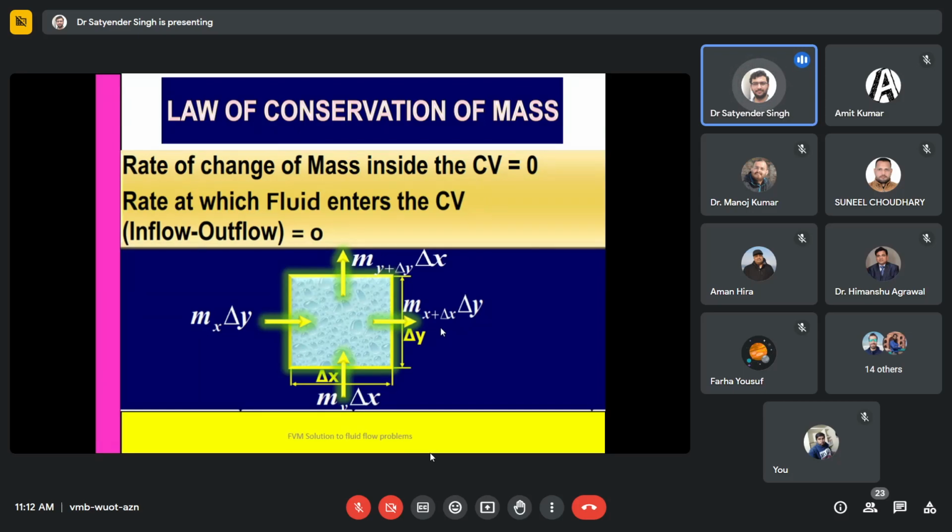The most important thing to mention is the use of this conservation of mass. Although we cannot derive any velocity from this mass balance, if you are using any CFD solver, the first thing you will see is the convergence of the continuity equation. The importance of conservation of mass in all solutions of fluid flow problems is that we check the velocities derived from the momentum equation using any of the algorithms.